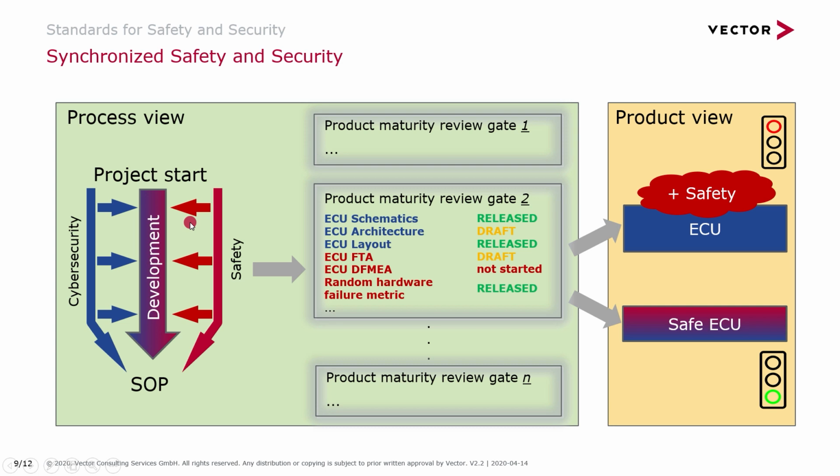Then we have a safety concept, and the safety concept has to relate to the security concept. And on we go throughout the life cycle. Even when we talk about testing, a pen test from a security perspective should first and above all ensure that we cannot harm a safety goal by any way of external manipulation. That means we have a lot of these synchronization points along the life cycle, not the least, of course, when we talk about the software update management, which I just explained with UNECE WP29.